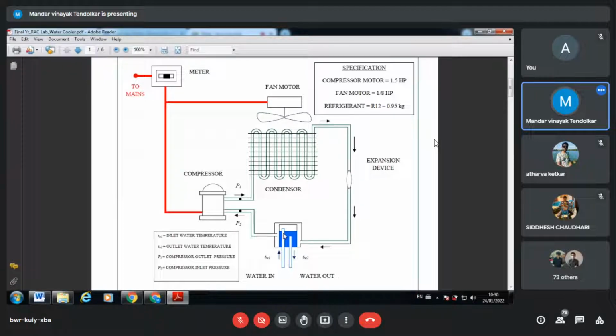Delta T is the final effect depending on the m dot. If we change the m dot, delta T will change accordingly because your inlet is constant. So the higher the m dot, the lower the delta T. The lower the m dot, the higher the delta T. Do you agree? M dot Cp delta T. So is the water side clear?